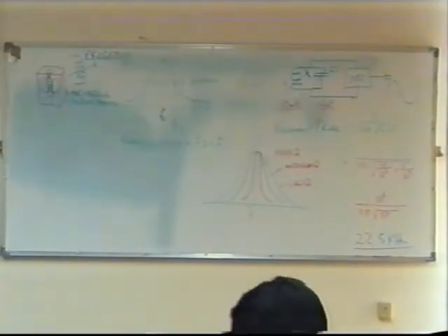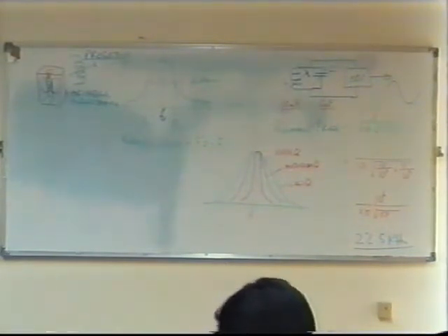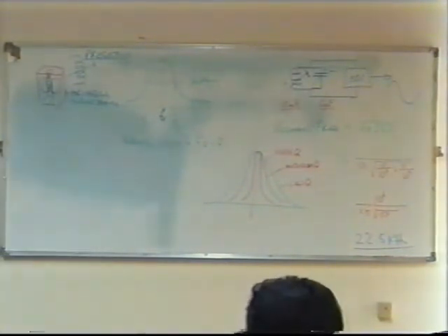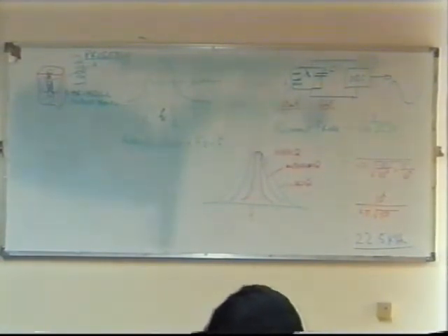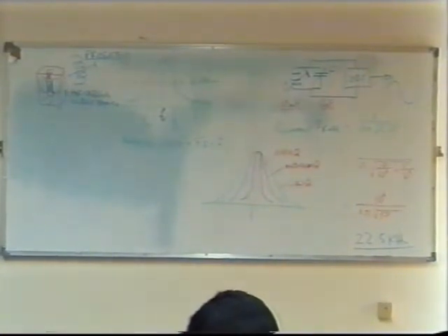Yes. If you've had any experience at all in radio, you'll be very familiar with this sort of thing. The metal can is like a shield, isn't it, to prevent the field. Yes, and it should be grounded as well, because it's also affecting capacitance as well as inductance, in fact. Anyway, that's a variable or preset inductor, which you very often find in radio circuits.